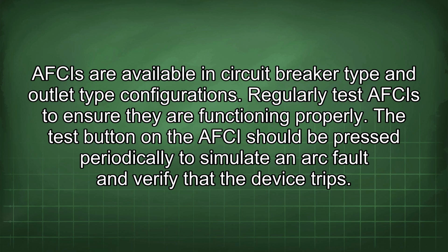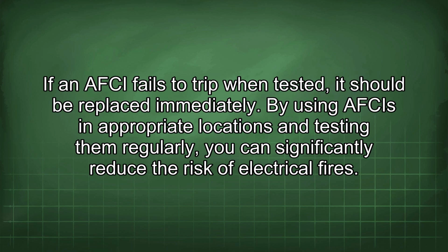Regularly test AFCIs to ensure they are functioning properly. The test button on the AFCI should be pressed periodically to simulate an arc fault and verify that the device trips. If an AFCI fails to trip when tested, it should be replaced immediately. By using AFCIs in appropriate locations and testing them regularly, you can significantly reduce the risk of electrical fires.